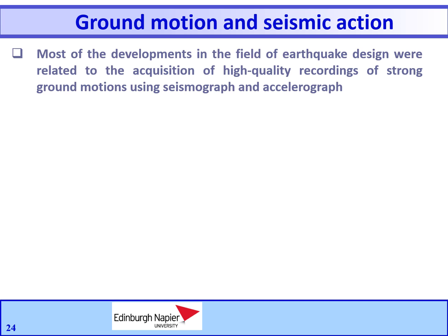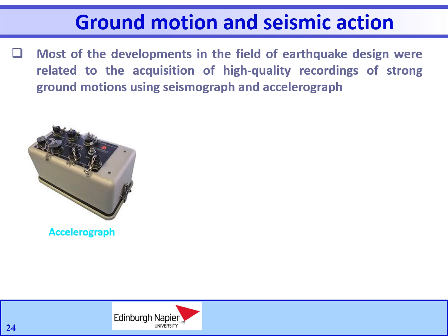Although measuring instruments are highly developed and intricate, the basic element of these instruments is some form of a transducer. In its simplest form, it is a transducer, like a mass spring damper system, mounted inside a rigid frame that is attached to the surface whose motion is to be measured.